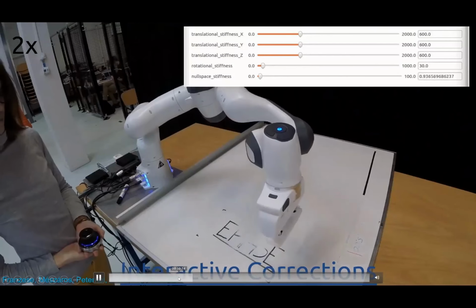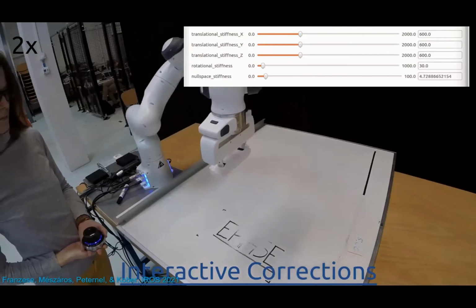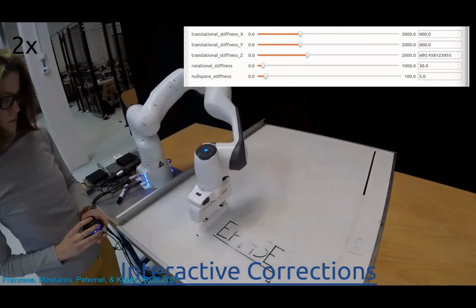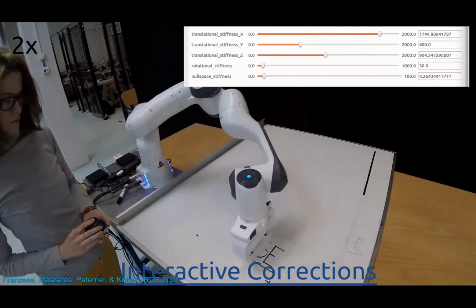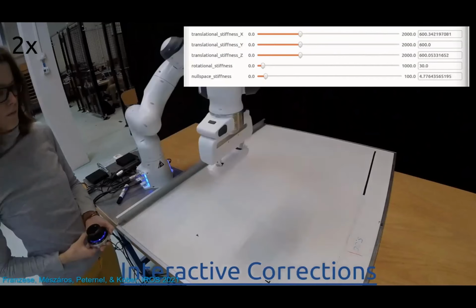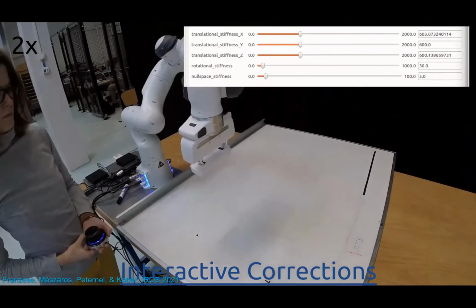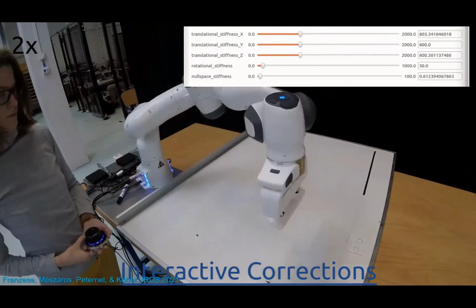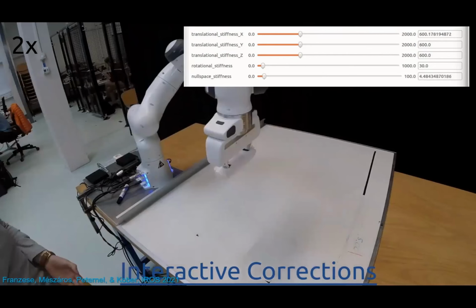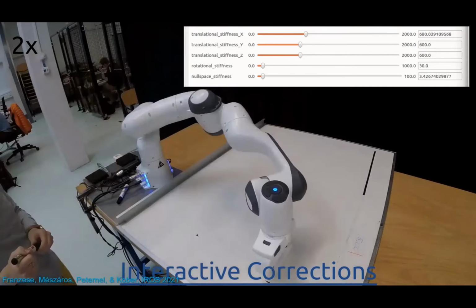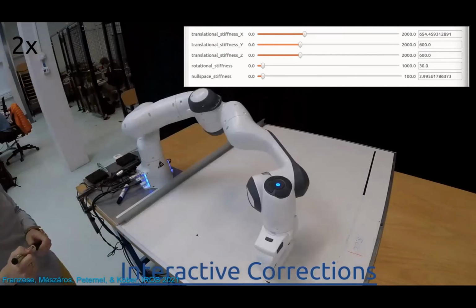Because we're just using the position as feedback, we don't have a separate force torque sensor in the robot. So if you're doing kinesthetic demonstrations, you can't rely on the torque sensors in the joints. So initially it didn't know that it actually needs to push down. So Anna was giving a few corrections while it's on the table to move it even further into the table and hence to exert the force, and then we just saw in real time how quickly you can adapt that.